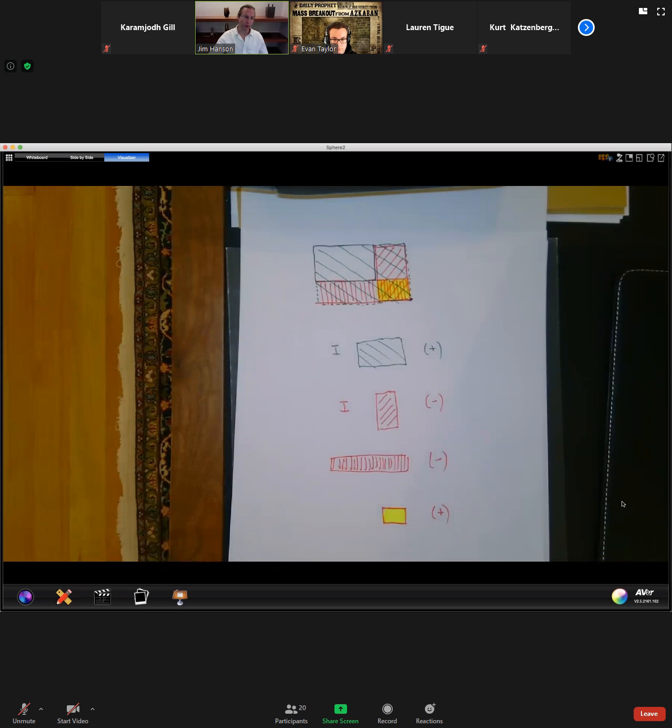And therefore, with the M and N chart alone, you have a great power to establish what is the stress change anywhere under a rectangularly loaded foundation. So it's a highly capable methodology if you take it to its limit and utilize it in this fashion.